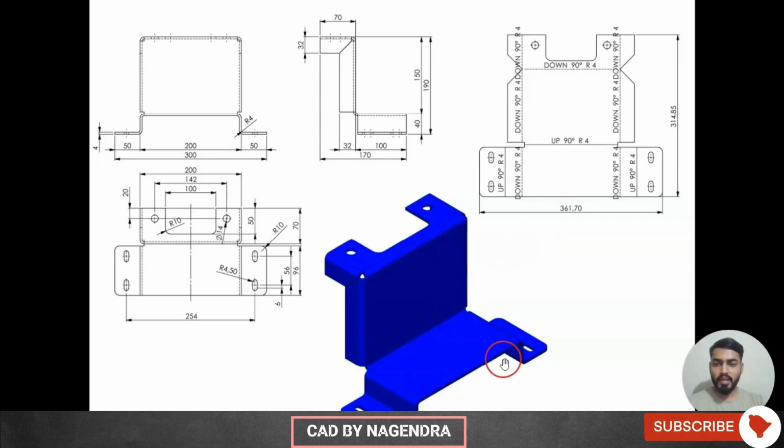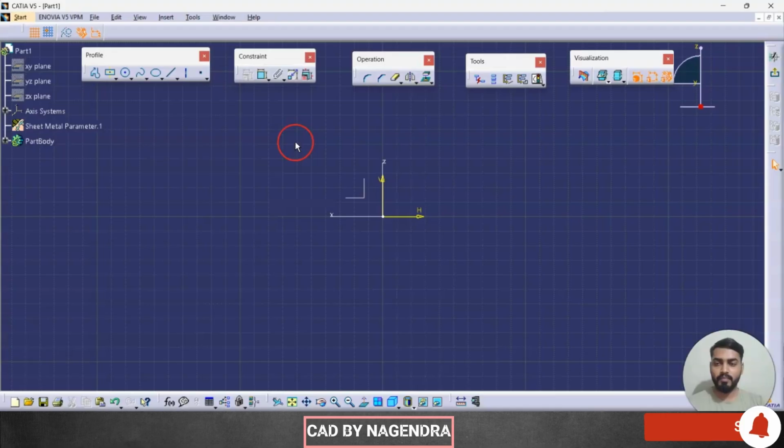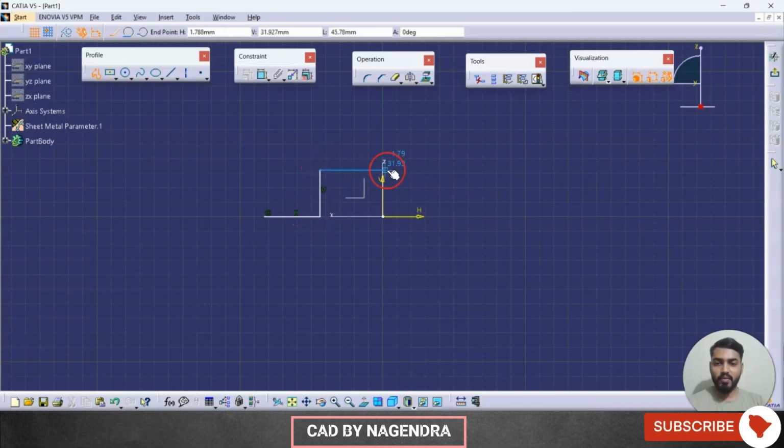Now to create this step, I'll go here with this profile. I'll start somewhere from here, horizontal, then vertical, again horizontal, then again vertical, then up to here. Let's escape. Then let me apply relations using Constraint.